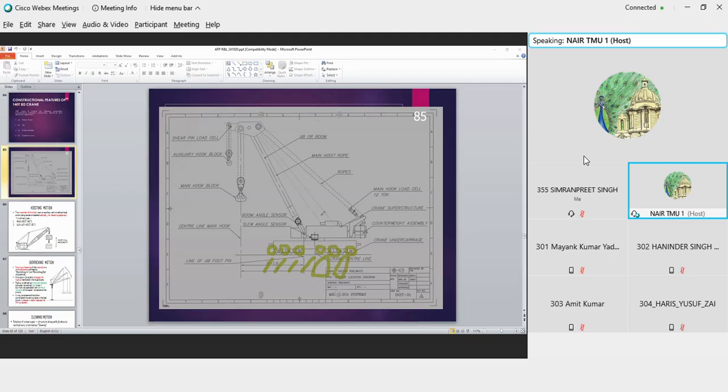The load, when it is getting lifted from the hoist here, would be coming on these arms. So these arms would be taking the load, and this load would be going down to the earth through these arms. And this activity is called propping. So you prop the crane, you make the crane free on rails, and the load starts getting transmitted through these props.